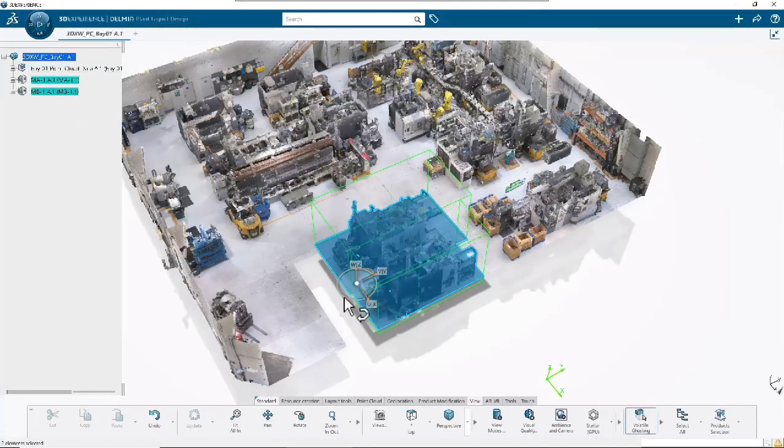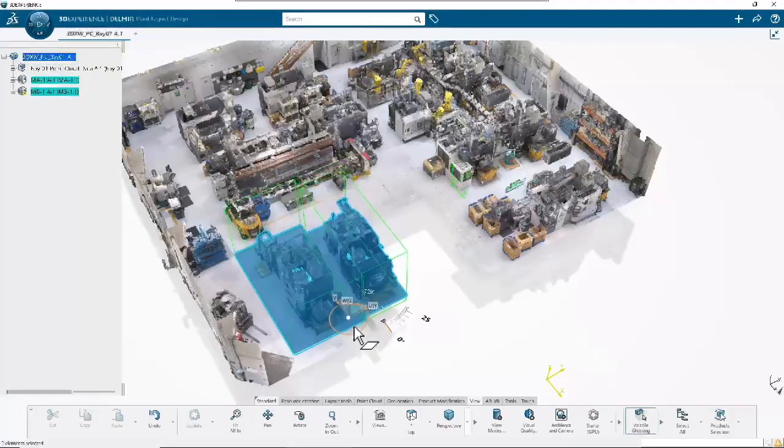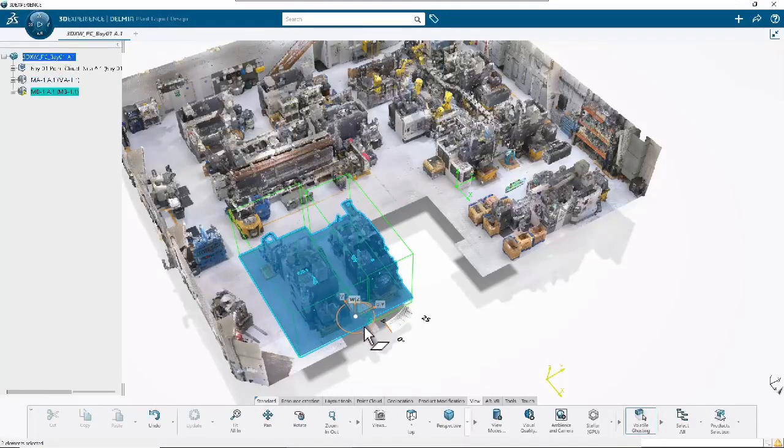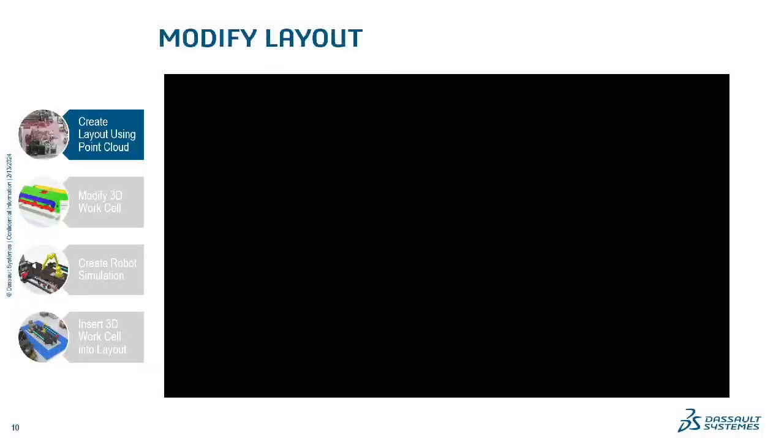So typically when you're working with point cloud, it doesn't have a good reference frame. So you want to drag the triad onto the area you're trying to move and then move them. Here I'm doing it separately, or together, you could do it separately, but it just gives you a better point. Otherwise that reference frame is floating in space. So you just drag it on, select both of them from the tree.